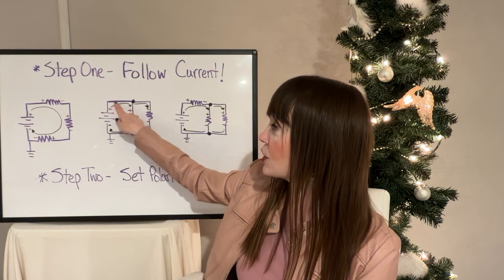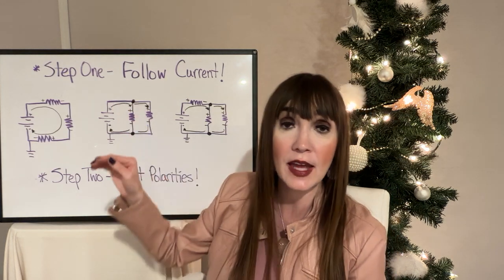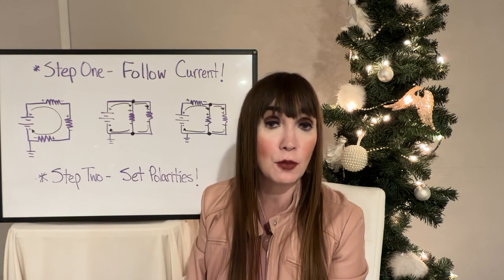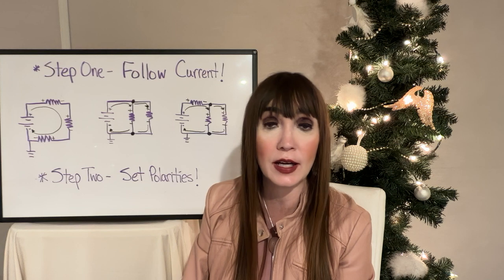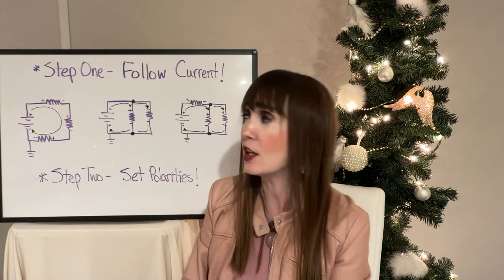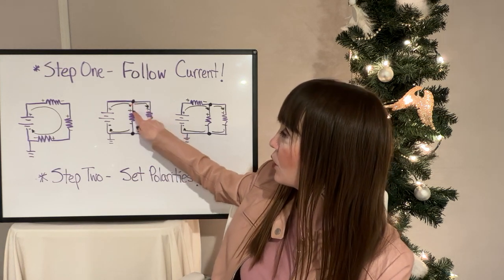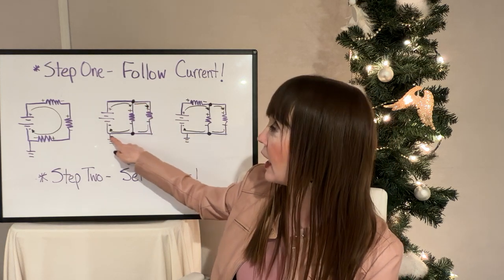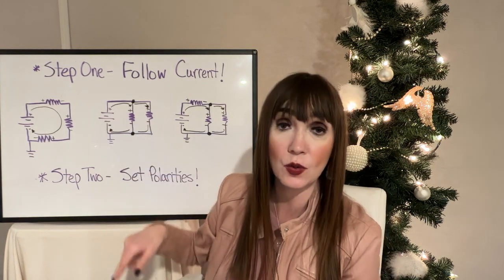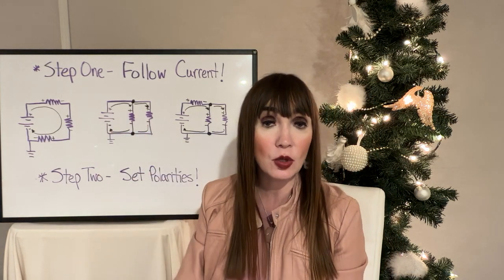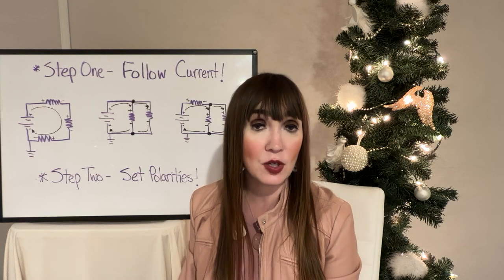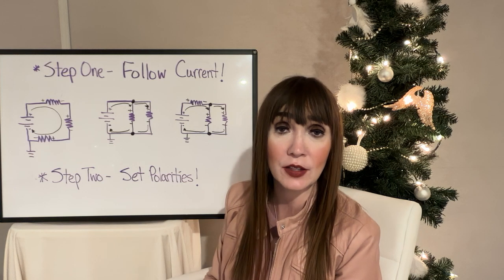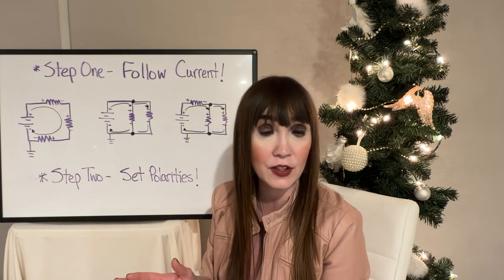I total is flowing at this point, but then I total divides, and it has to because it has two branches that it's able to divide through. Then it returns back, and I total returns back to the source. But now we can no longer use I total in some of our calculations with this parallel network, so we need to be mindful of that.